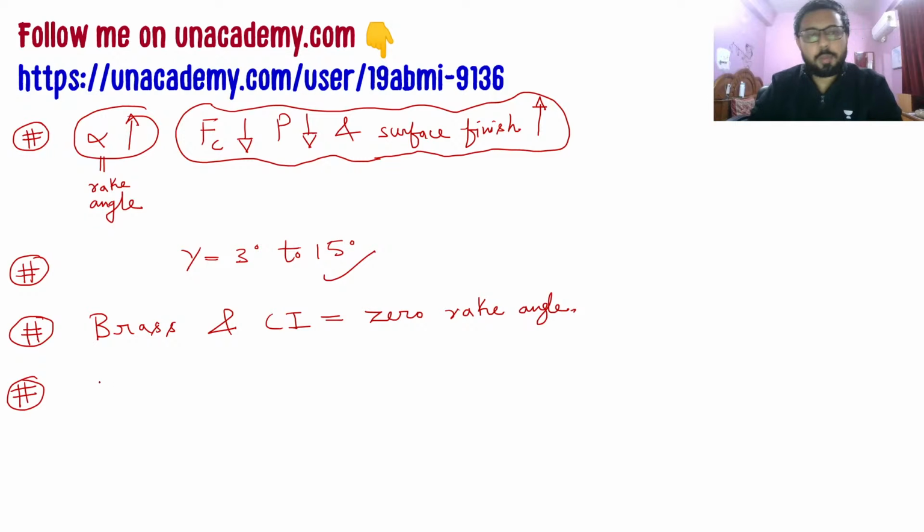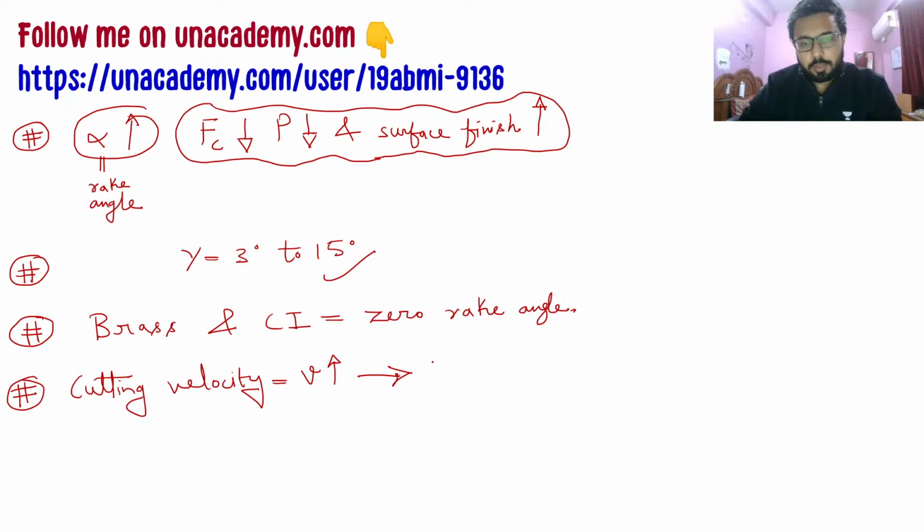I also talked about cutting speed. If cutting speed or cutting velocity V increases, then you will find that power will increase and therefore temperature will go up.